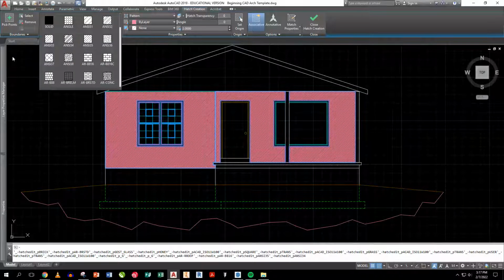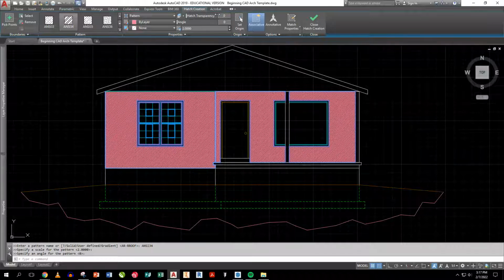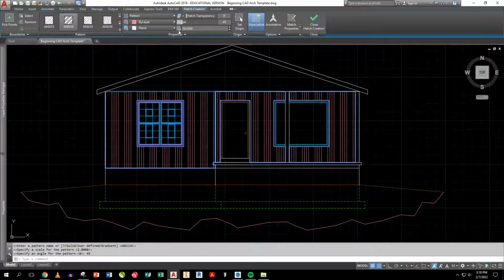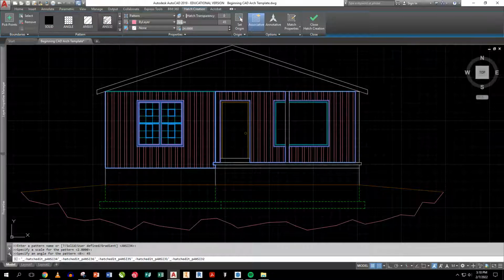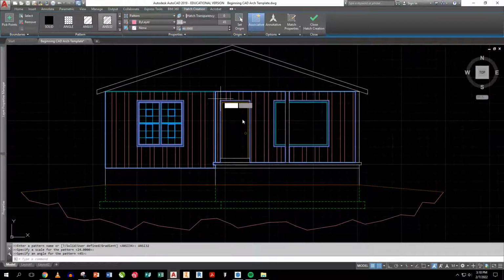But for what we're looking at here, I actually don't want brick on this house because it's a starter home. I'm going to change the angle here to 45 degrees so it goes up and down. Remember, it rotates around that axis. And I'm going to change that to be a 24. I'm trying to mess with my numbers here, so it looks like I've got a vertical siding. That looks a little better, but I'll probably have to up my stuff to 48. And that looks like a version of a batten board siding. So if that works for you, that's great.